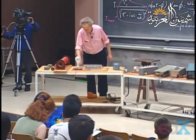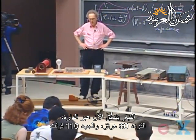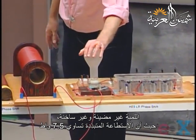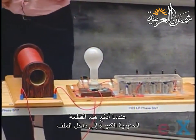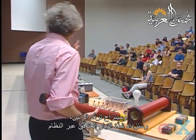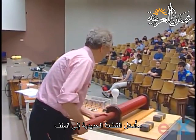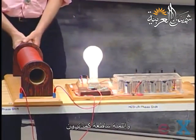All right, so here, the system is now, current is going. 60 hertz, 110 volts, root mean square as we call that, and it's way off resonance, 7.5 watts, the light bulb doesn't even feel warm. And now I bring this enormous piece of iron in there, and when I shove it in, the self-inductance will slowly go up, the resonance frequency will shift, and the current through the system will increase. And there we go. There it is. I'm on resonance now. So the light bulb is quite happy.